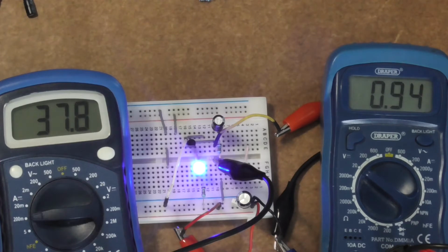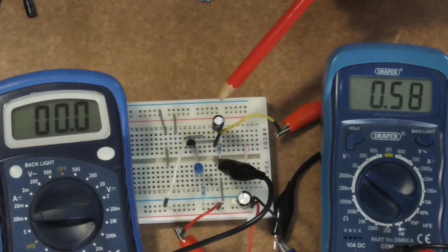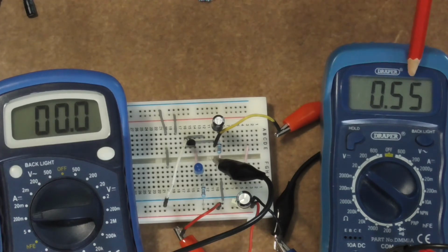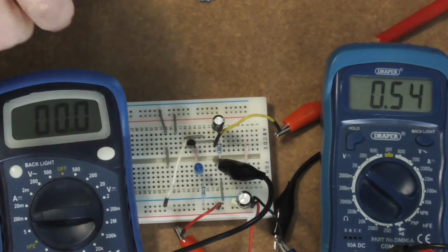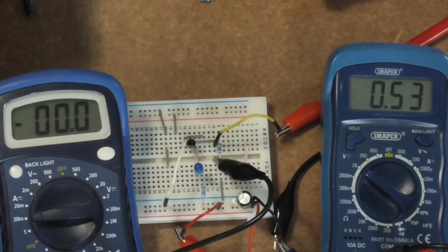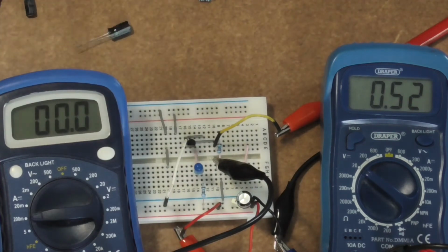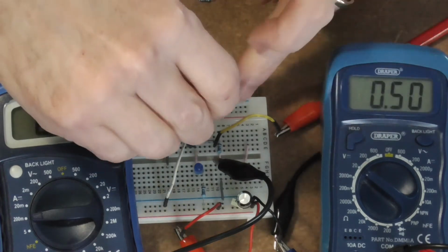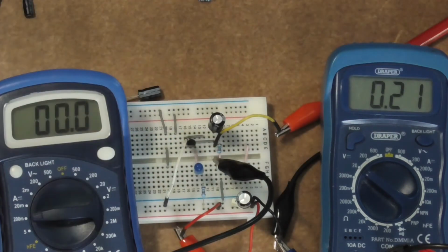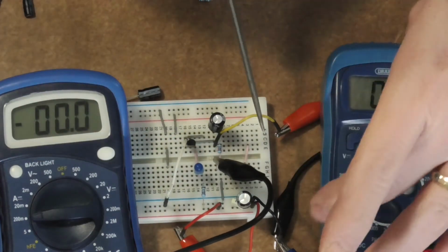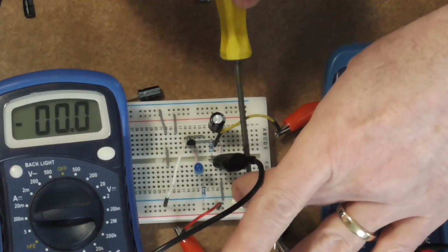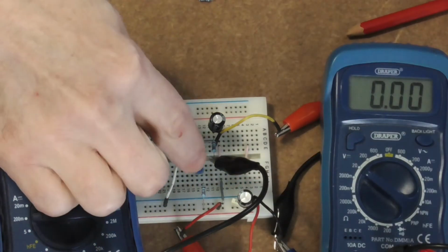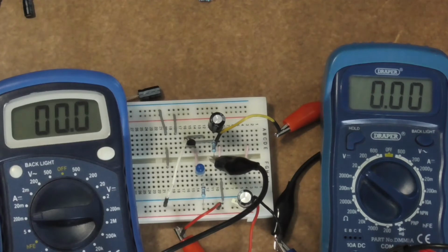But is it taking time to charge up? At the moment I'm not seeing that. I'm not seeing a charge time. It is slowly discharging, so there is a discharge time, but let's pull it out and go up to the 330 microfarad. Get that in there. Just take out the charge on that capacitor and turn it on and see how quickly or slowly it turns on.